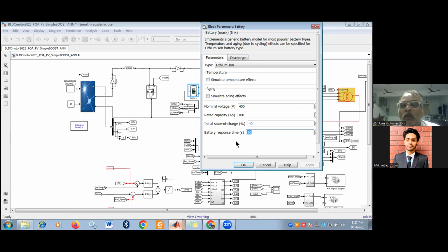We also have to assure the temperature of the battery. We should not increase the charging current. When the battery voltage is very low and the SOC is very low, whenever we give the voltage for charging, the charging current can become very high.